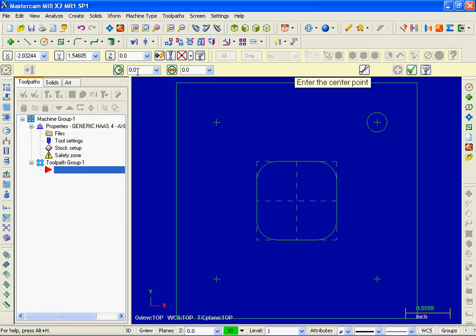So I'm going to click in the white space for radius and input 0.25 and then hit enter. Now to satisfy this prompt, enter the center point, I'm going to move over, and as we move over this circle, there's the visual cue that identifies that I'm going to snap to the center of the circle that we just created. So I'm going to pick this point. It looks great.